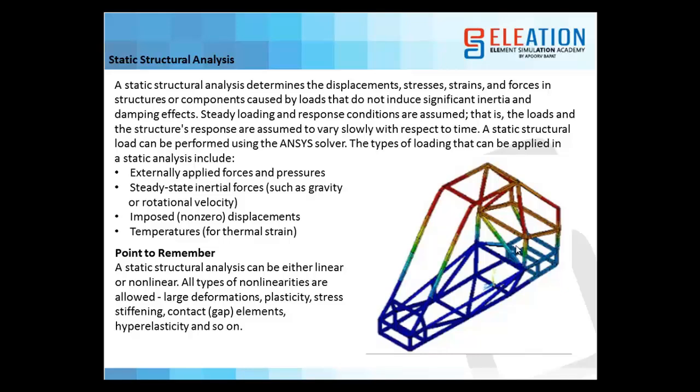A static structural analysis can be performed using the ANSYS solver. The types of loading that can be applied in a static analysis include external applied forces and pressure, steady state inertia forces such as gravity or rotational velocity, imposed non-zero displacement, or temperature for thermal strain. Points to remember: a static structural analysis can be either linear or non-linear. All types of non-linearities are allowed: large deformation, plasticity, stress stiffening, contact, gap elements, hyperelasticity and so on.